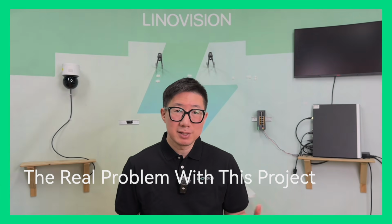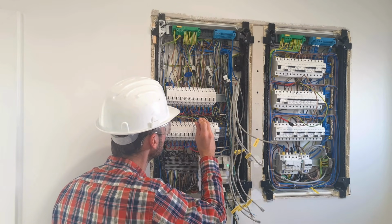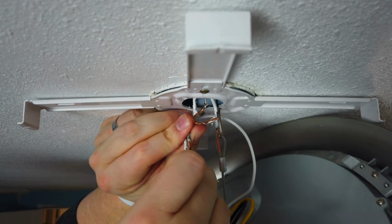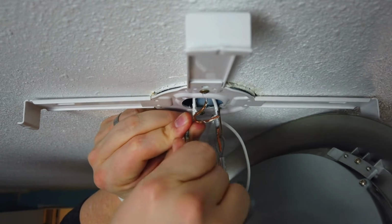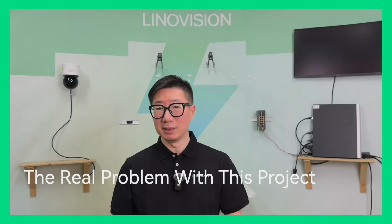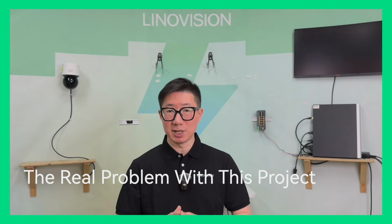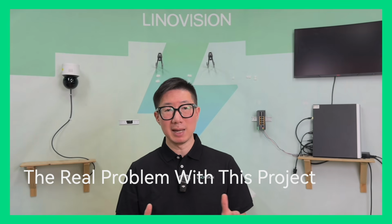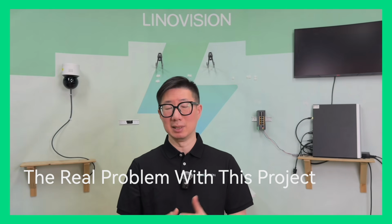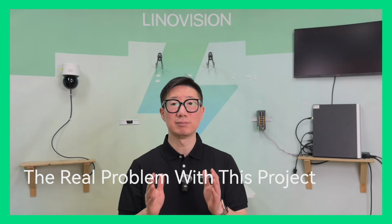In a traditional lighting system, your zones are defined by your electrical circuits: panel, branch circuit. That's the hierarchy. And that works fine as long as the layout doesn't change. But the moment the layout does change, and in a modern office it will, you're looking at circuit modifications, potentially new conduit runs, panel rebalancing, and what started as "can we adjust the lighting zones?" The conversation has just become an electrical project.